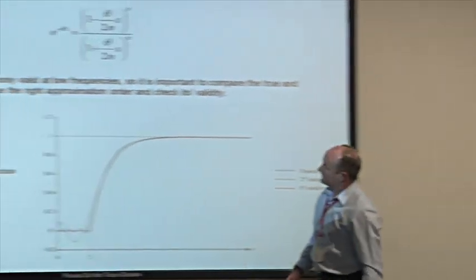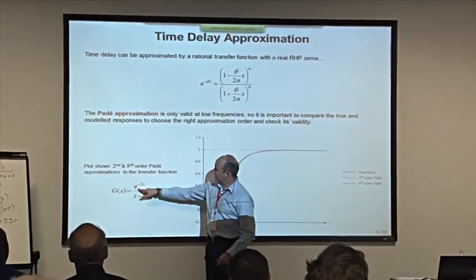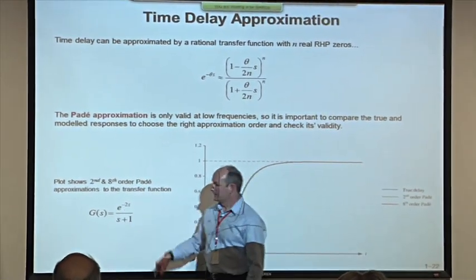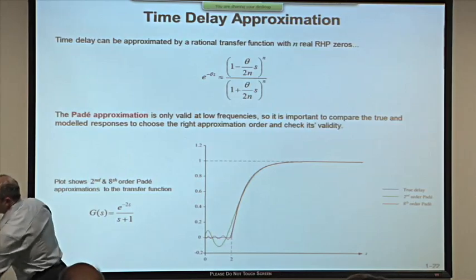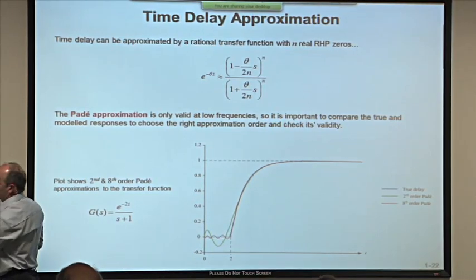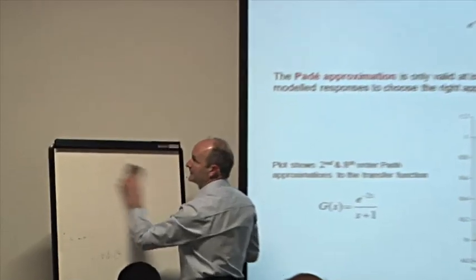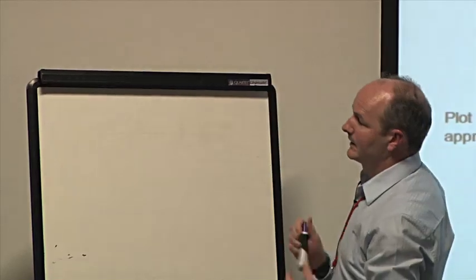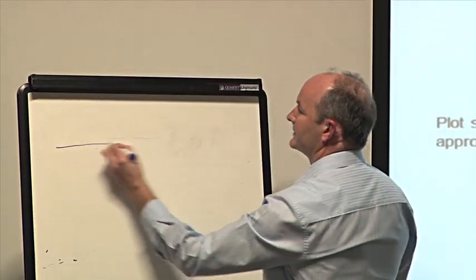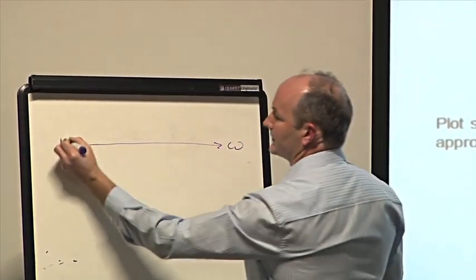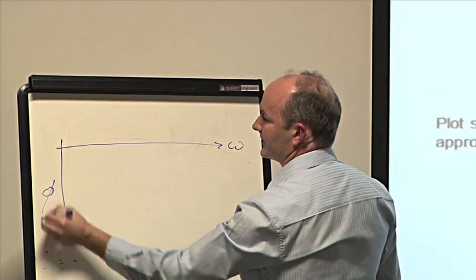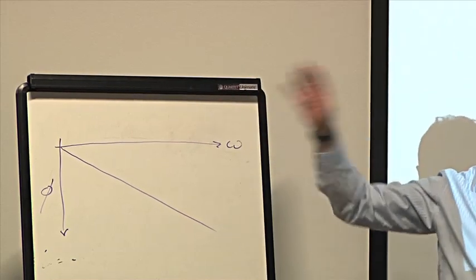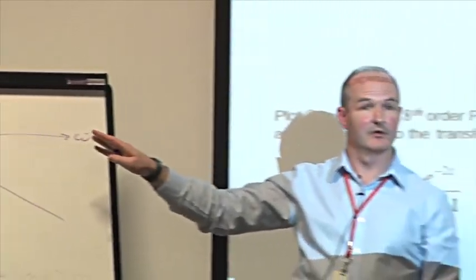Now, the phase, so you see, this is the time-shifting property that tells you the Laplace transform effect of a time delay. And what it means in the frequency domain is that a time delay has 0 effect on amplitude, it only affects phase. And the effect on phase is linear with frequency. So if I were to draw it on a graph of frequency versus phase, let's say, I would have a perfectly linear, perfectly straight line. That's the effect on phase of time delay.